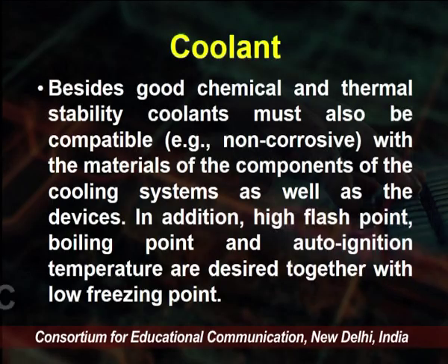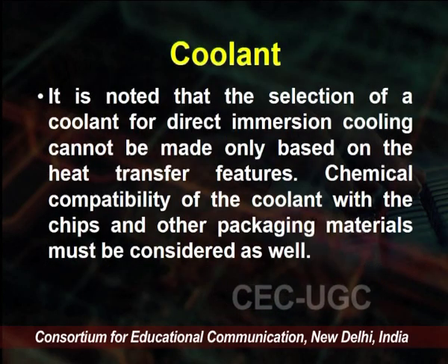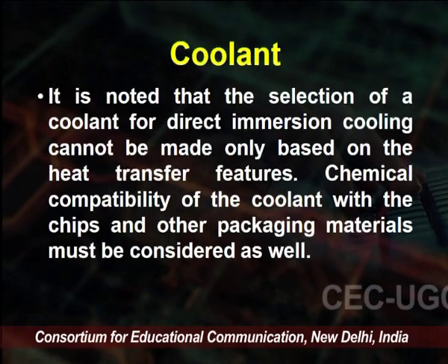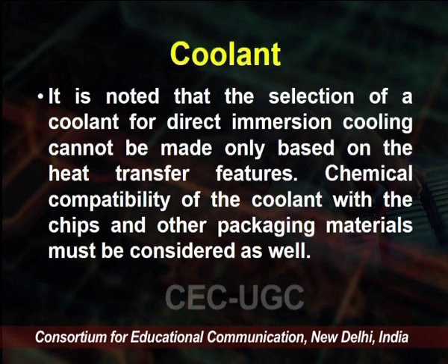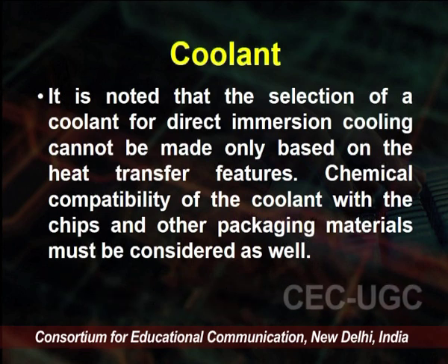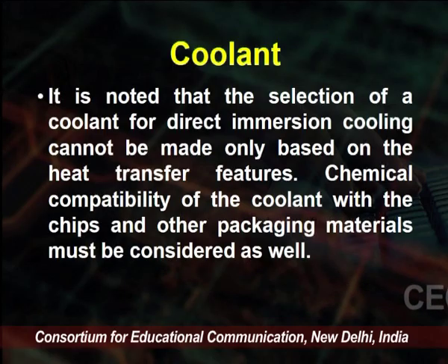In addition, a high flash point, boiling point and auto-ignition temperature are desired together with a low freezing point. It is also noted that the selection of the coolant for direct immersion cooling cannot be made by only using the heat transfer feature.